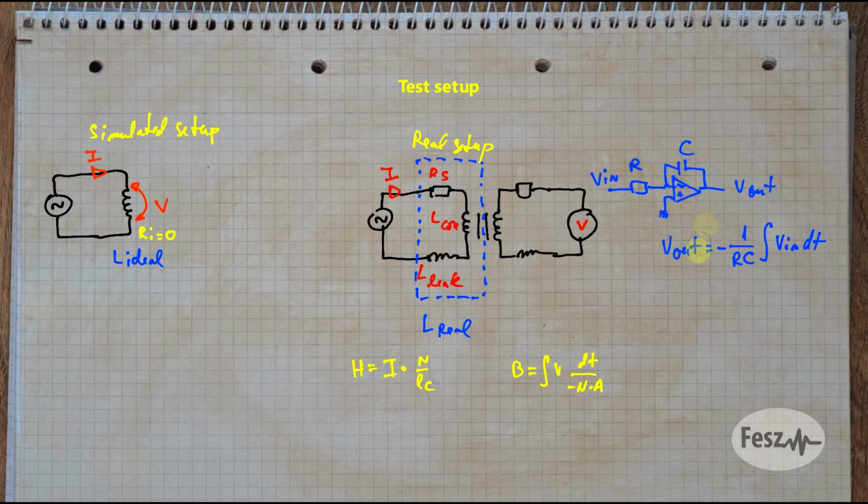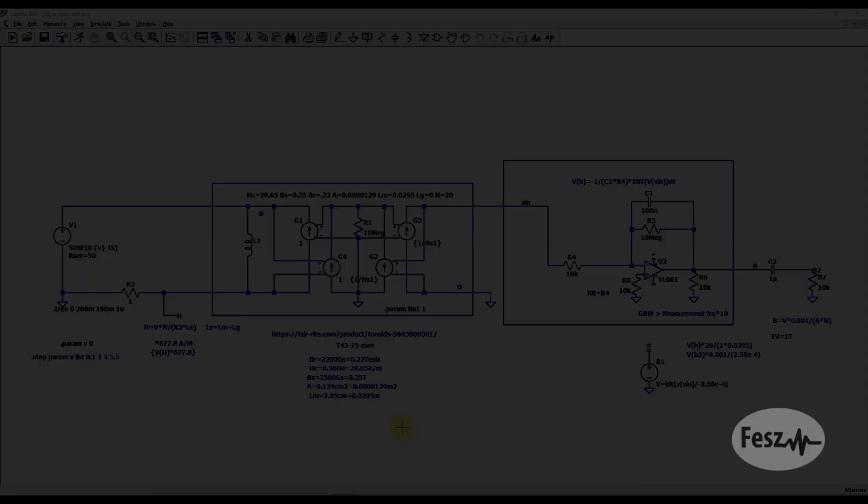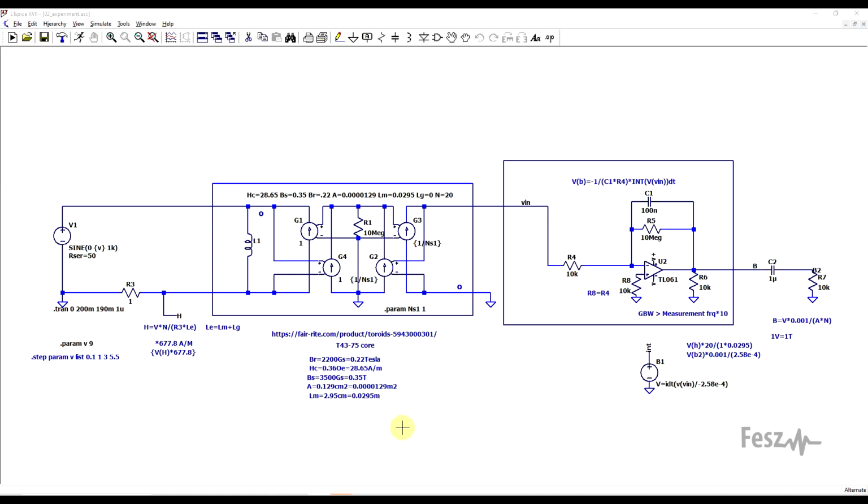So we can build an op-amp based integrator. Now, especially if you have an old analog oscilloscope, or you just want to be able to display the graph directly without any extra processing, this integrator bit will be necessary. Before building anything, I decided to check the operation of the circuit in LTspice.